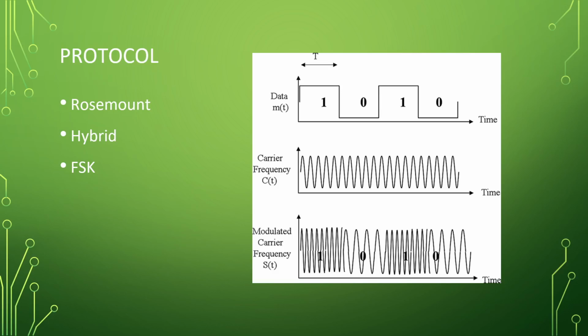And what we're doing is we have 2 individual frequencies, typically 1200 and 2200 hertz. All right. And that's what you can see going on here. So there is your 2200 hertz. There's your 1200. 2200. All right. So the 2200 represents a 1 and the 1200 represents a 0. All right. And because we are just superimposing this on there, we're not actually changing the current flow, because we have high and low current, by doing this, it still averages out to be the same signal being sent.